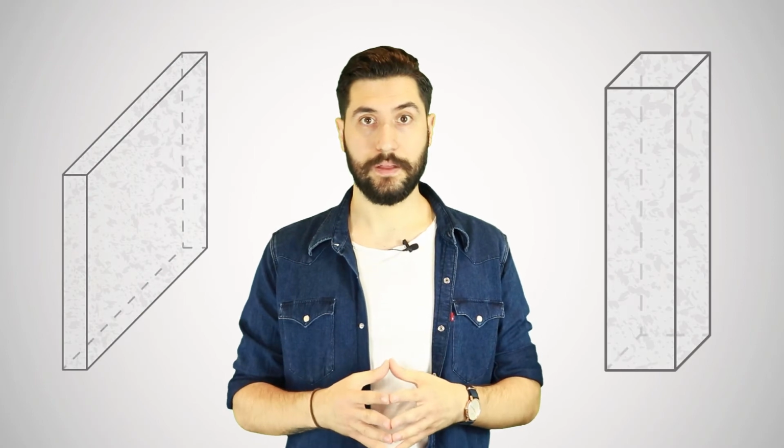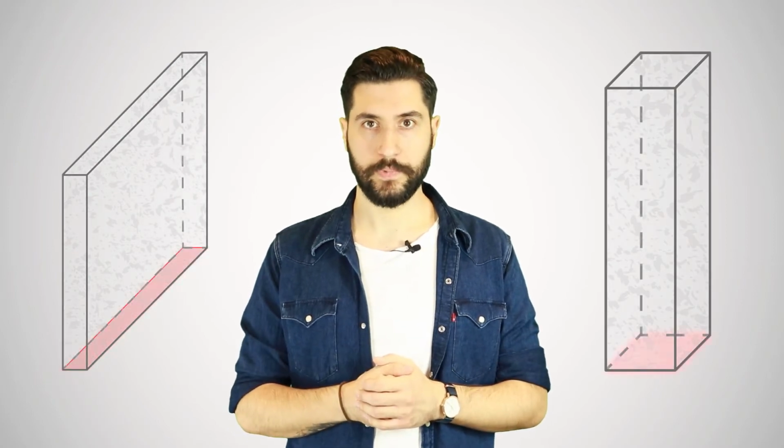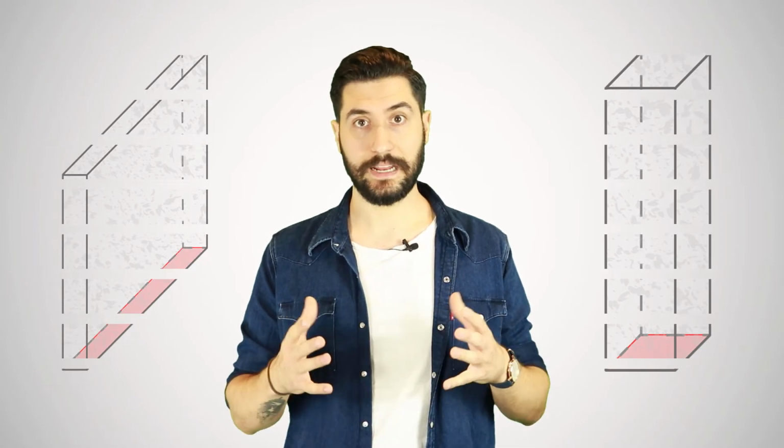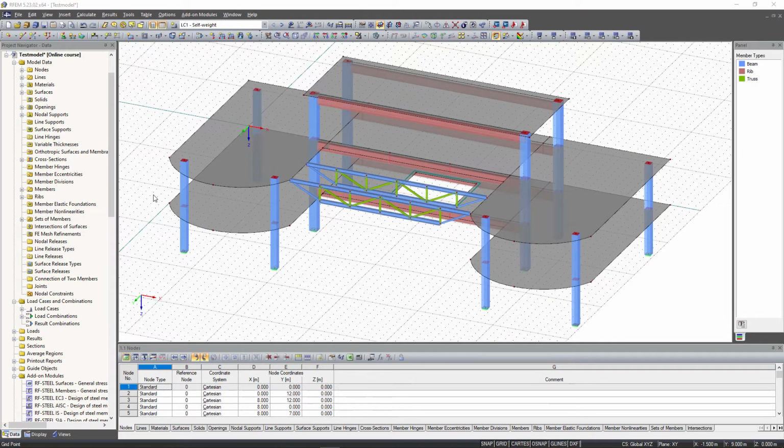Point loads and line loads do not really exist, because all structural components or bodies have an action surface, albeit a very small one. Simplifying and on the safe side, we do not consider them as surface loads, but idealize them. In the practical implementation in the structural analysis software RFEM, it looks something like this.